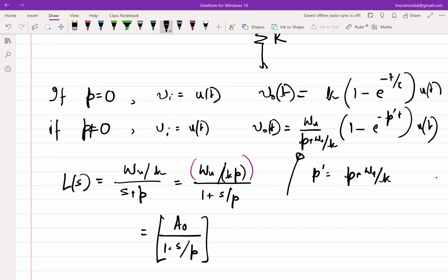Now, this is fundamentally true for a first order all pole system. This is not fundamentally true for any higher order system. But the systems that we will be using in this class will not be first order, and they will also not be generic. They will have characteristics in which this statement becomes sort of true for most cases. We will postulate that for most systems that we are interested in, as long as you figure out what omega u loop is, then regardless of the order of the system, the 3 dB bandwidth of the closed loop system will translate to the UGB of the open loop system, or vice versa. This is what we'll postulate. You should note that this is a rule of thumb, because this is not fundamentally true.